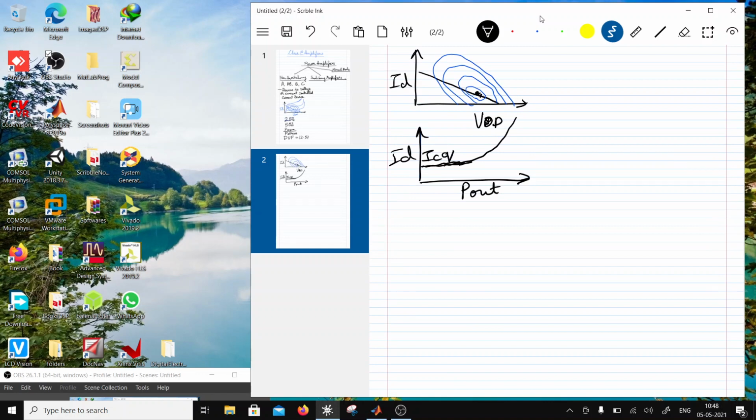So if you were to plot the gain versus P out, what's going to happen is, for a class AB, because the gain is going to increase with the bias, it's going to increase and then it is going to compress, right? So let me match the curves.